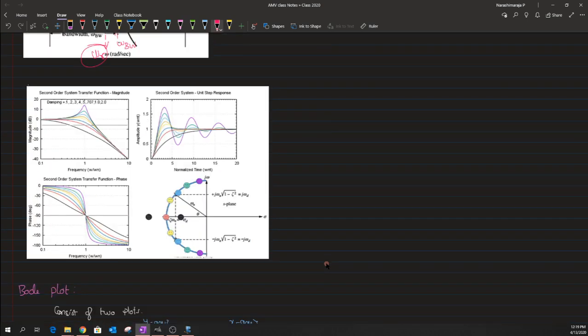And next comes the same thing. For a second order system, we have this purple color denoting a complex conjugate pole, but with a smaller magnitude of real part. Here the real part is small, which means the rate at which it dies out would be pretty small.